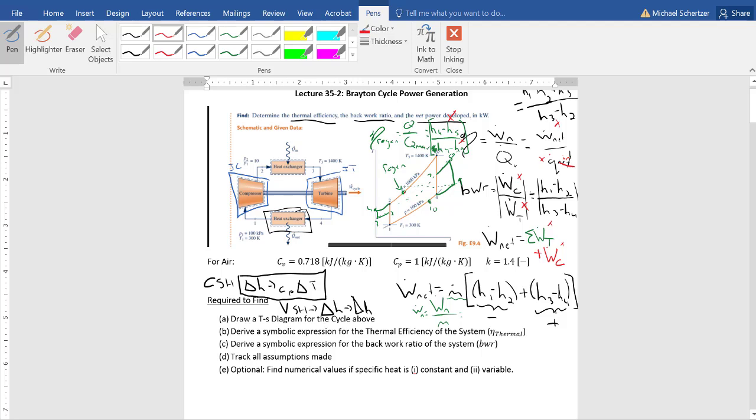So at that point, when you feel stuck, you go to the inlet of the first turbine, because just like in this problem, they'll usually give you the temperature going into the first turbine. So you leave state 5 for a second, and then you go through the first turbine, and then you know something about the reheat. Maybe they tell you T8 too. You go through the second turbine, and then partway through the problem, you'll figure out H9.